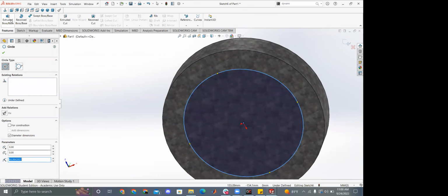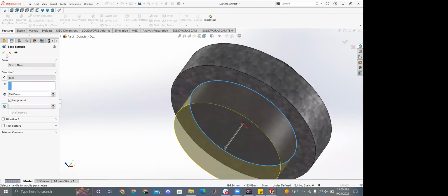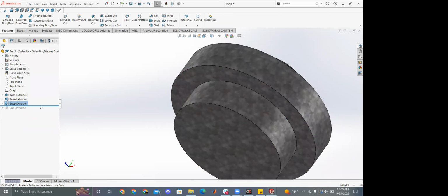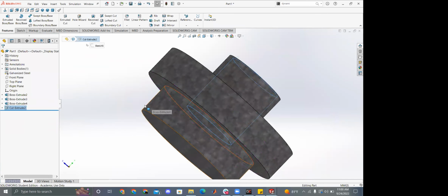Now when I roll it forward, even if I delete this hole, it will still function and not break. Versus if I put it at the end, there would be a possibility of it breaking, because coming later, it could be dependent on that earlier feature, maybe accidentally relating to a line or being on a face that the last feature created. So yeah.